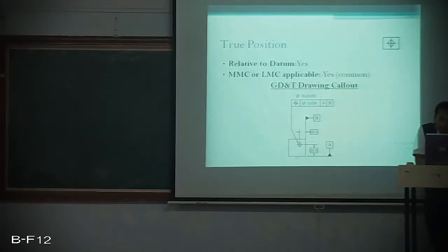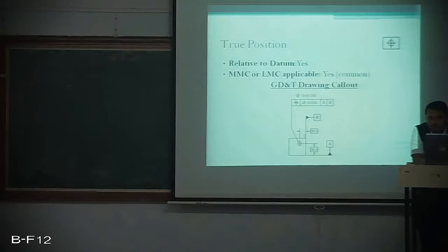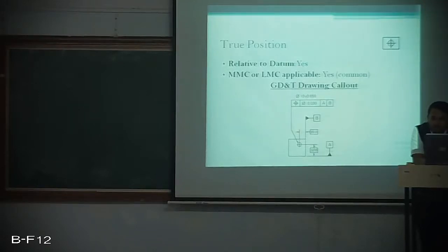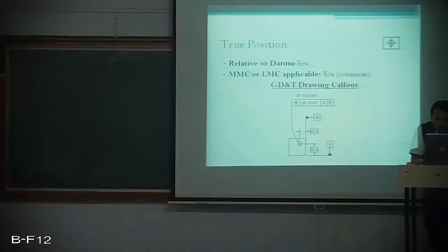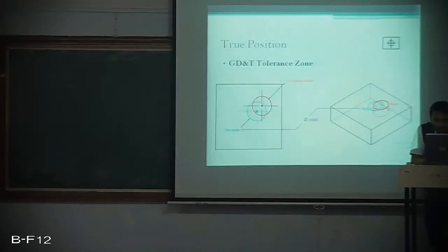With respect to A and B, because the central axis dimension is given from this bottom surface, I am taking this as datum A, and from the right surface also they have given the central axis dimension, hence I am taking it as datum B. The coordinates of the point have to be mentioned in the x and y directions, hence they are mentioned in two directions, and those two surfaces I have taken as reference planes, or datums, A and B. So now,